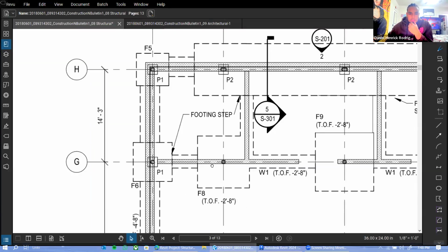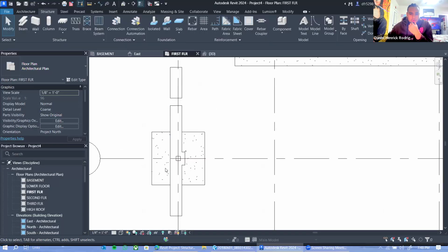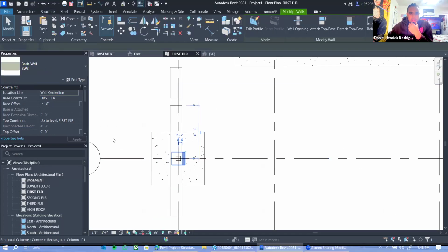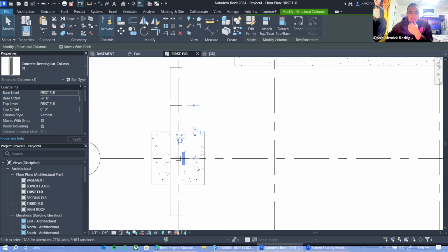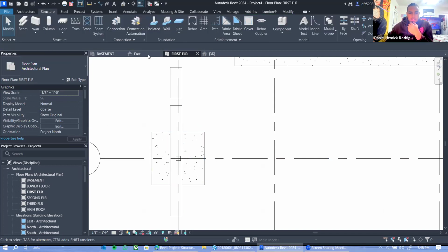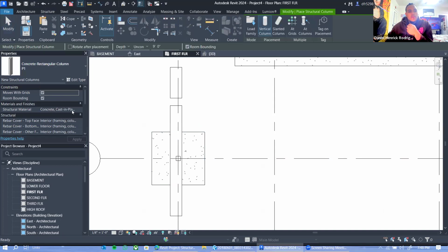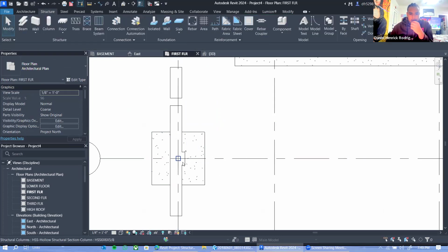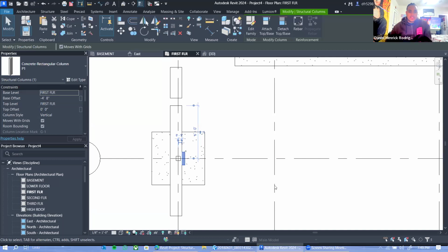So first of all, just check, we're still at -4.8, so the wall is at -4.8. The pier automatically goes to -9. Let me actually delete the pier, and when you're placing it, if you give it the height that you want, next time you place it, it will be the same height. So let's put -4.8 here before we even do this, and then put the pier down. There we go. Now the base offset's -4.8 right away.